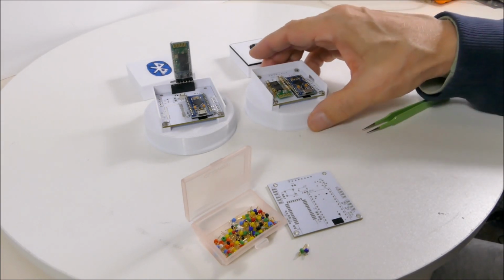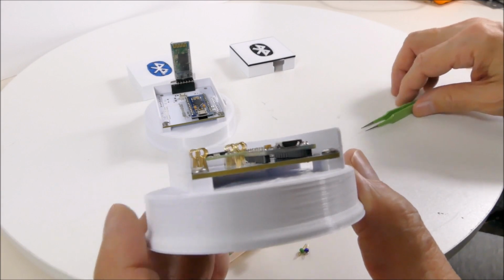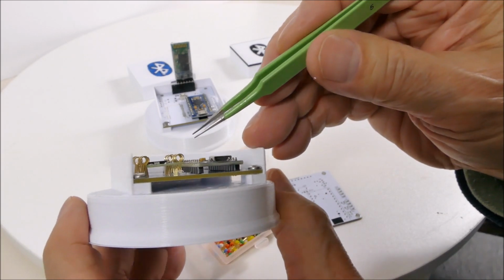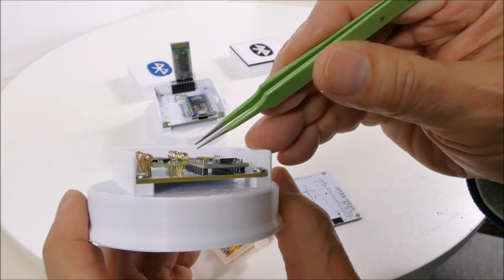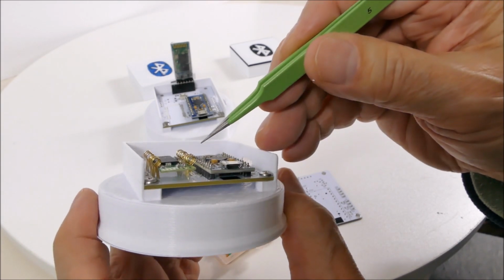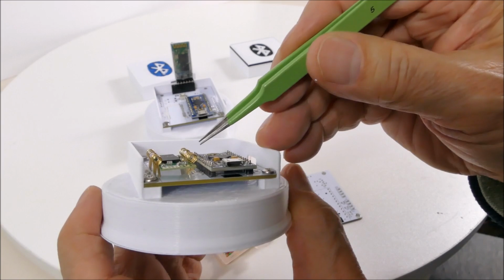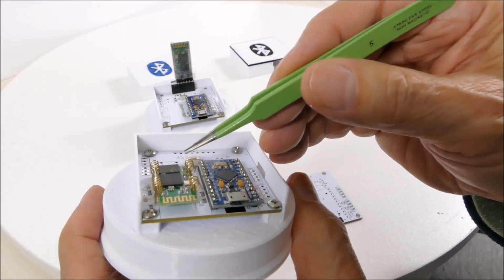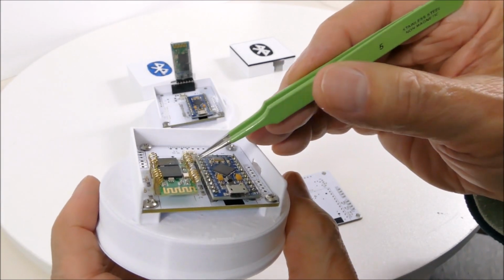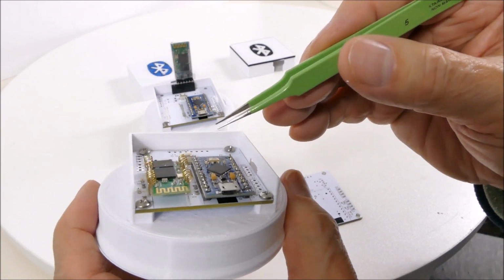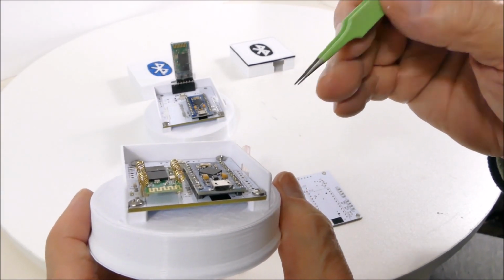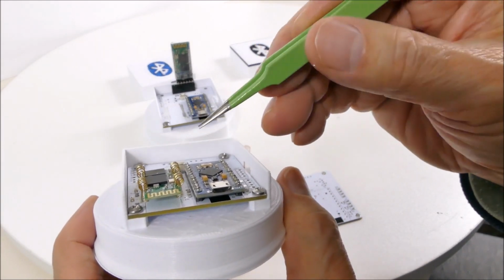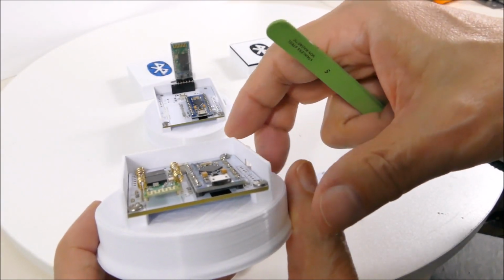And the way I do that on the castellated one is with these fancy pins, which are just spring-loaded to fit into the notches in the castellated edge. So I had ordered some expensive flexi pins to do this, but I promptly squirreled them away somewhere where I couldn't find them. And what I ended up with is just using these test points.